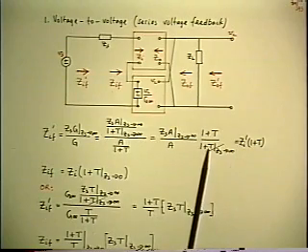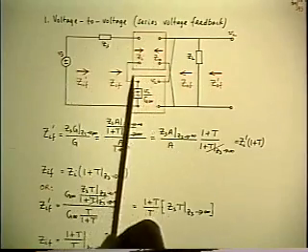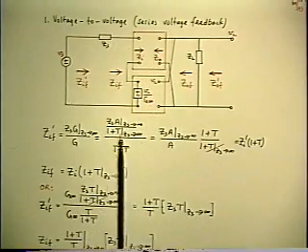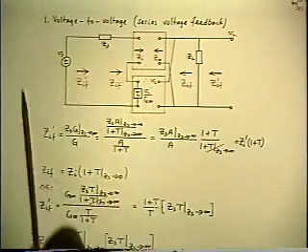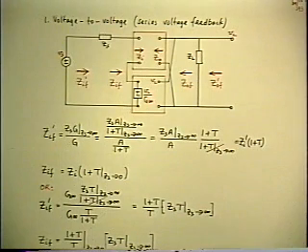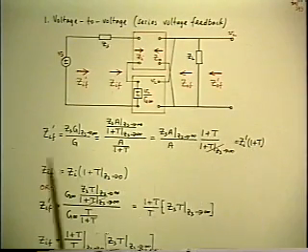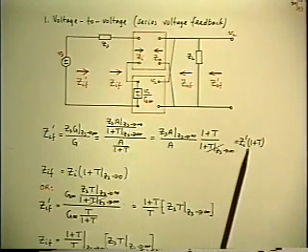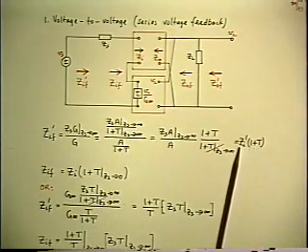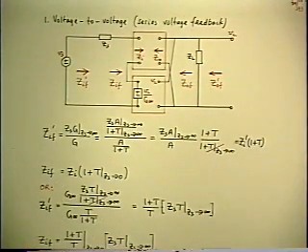Look at what's left. One of them is T as Zs goes to infinity, which must be 0. Because if you let Zs go to infinity, you're opening the voltage differencing loop and killing the loop again. So that must be 0. And all that's left is the 1 plus T. And you get the well-known result that series voltage feedback to the input raises the outside input impedance from its open loop value to its closed loop value by the feedback factor.